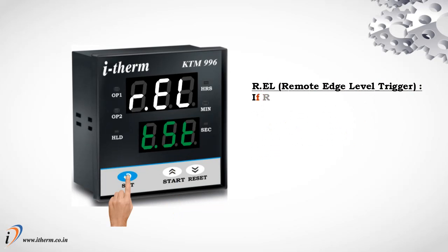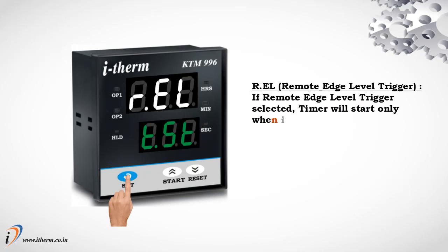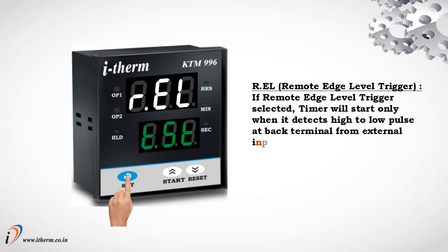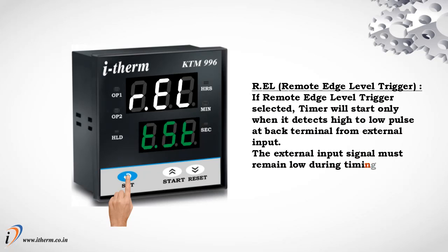Remote edge level trigger. If remote edge level trigger selected, timer will start only when it detects high to low pulse at back terminal from external input. The external input signal must remain low during timing cycle, otherwise timer will reset.